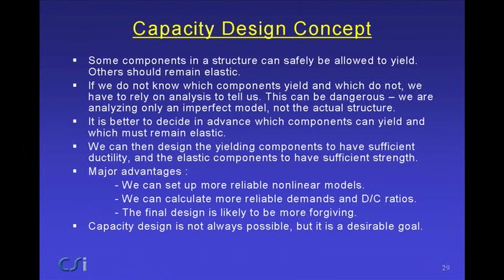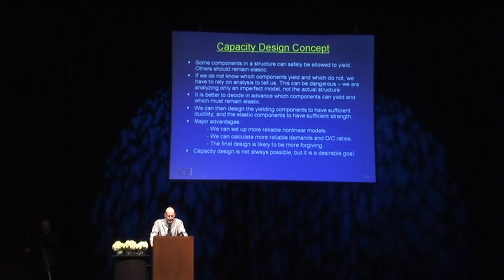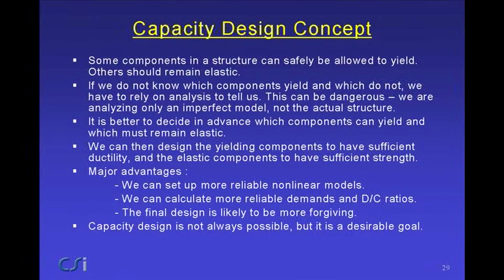Firstly, if you do this, you can set up a more reliable nonlinear model. If you know where the yield is going to occur, you have a much better chance of setting up a good analysis model. Secondly, you can calculate more reliable demands and demand capacity ratios. And finally, and probably just as important, the final design is likely to be a more forgiving design. That if the loading is a bit stronger than you expected, you're more likely to get proper behavior. And so it's a good, desirable design approach. It's not always possible, but it's a desirable goal.